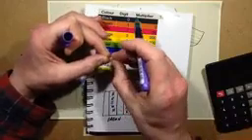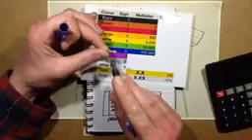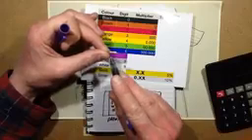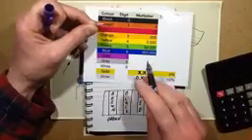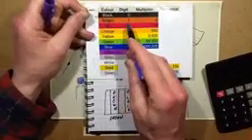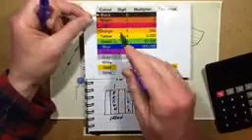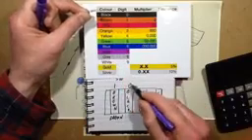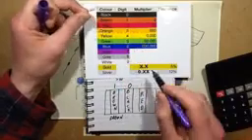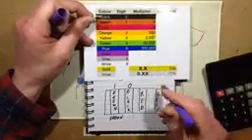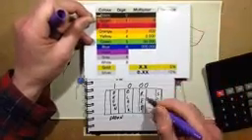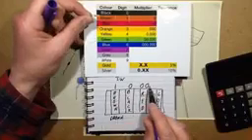The colour code itself is worked out like this. The first band is the first number. So in the case of brown, it means 1. The black means 0. And the red means 2. But the third band is actually a multiplier. So in the case of the red one, it means there's 2 zeros. 2 zeros equals 1000 ohms.